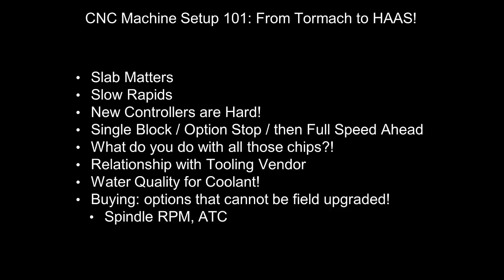We've been pushing the envelope with some things like Sandvik through spindle drills where we're going 15,000 RPM, 300 inches a minute with a half-inch drill, no pecking, and I want to have the machine wait for me to be there when I run that, if anything, just to have fun and watch it.